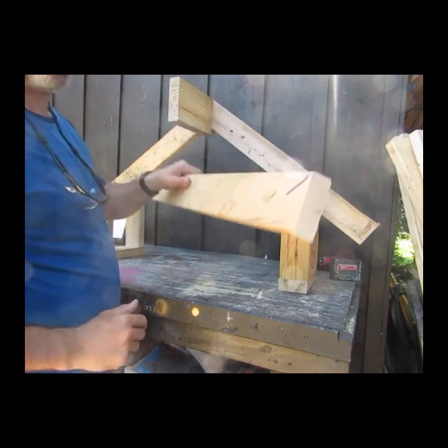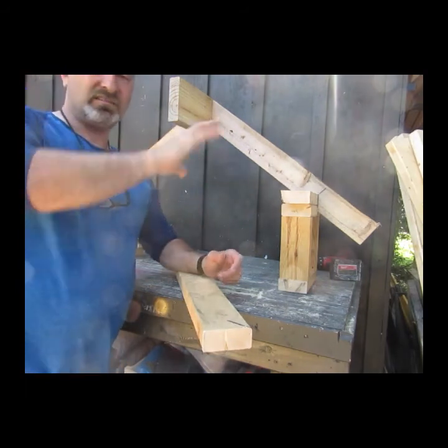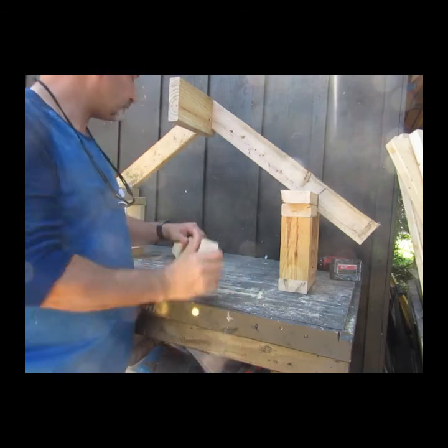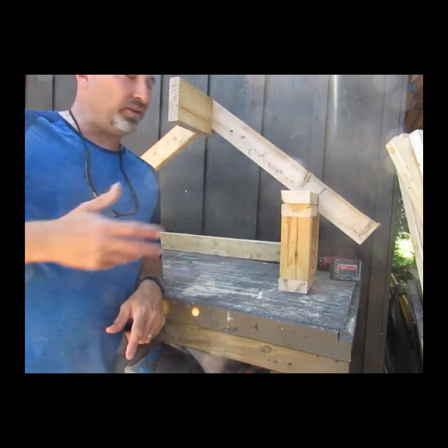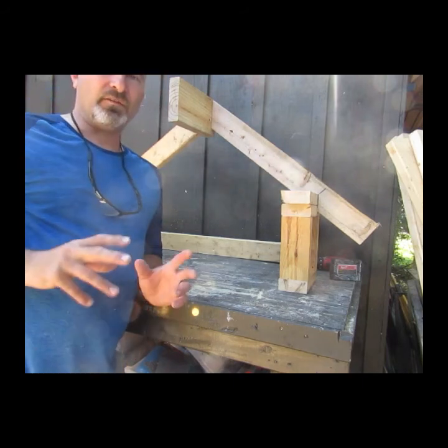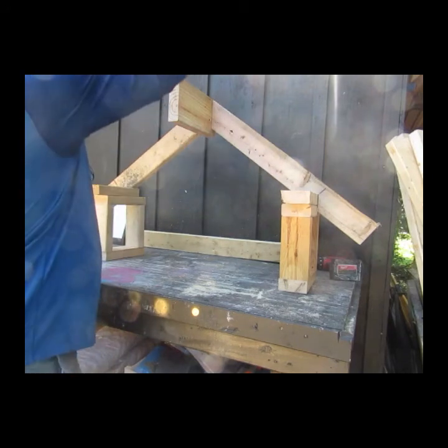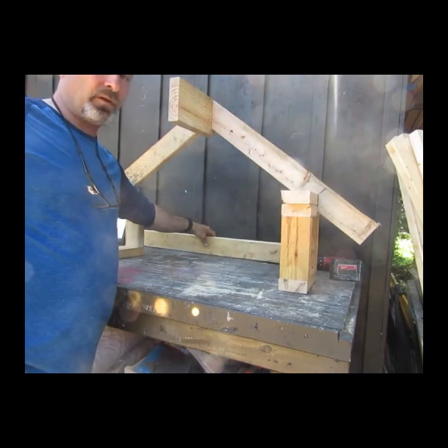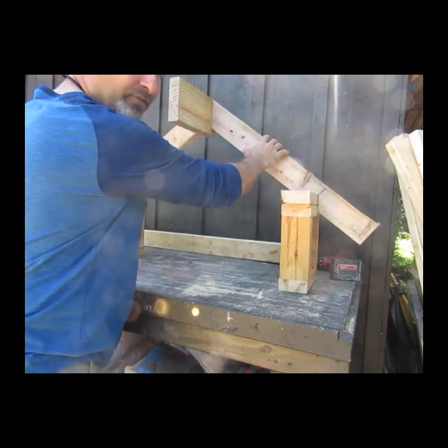Now, that's to hold the structure of the triangular rafter system, but it doesn't talk about stopping the walls from coming apart. Now, the bird's mouth is using the wood itself and the integrity of the fibers of the wood and how it goes together to resist the bending force. So this is pressing down and it's wanting to pull apart. This rafter tie is stopping it from being pulled apart, but at the same time, these walls need to be connected to the rafter system.